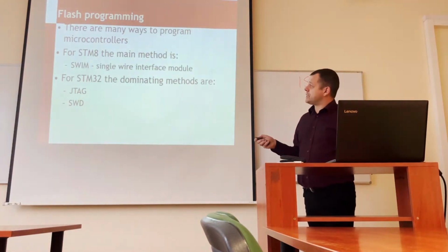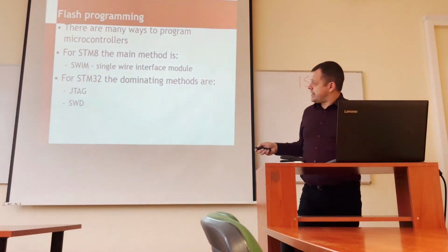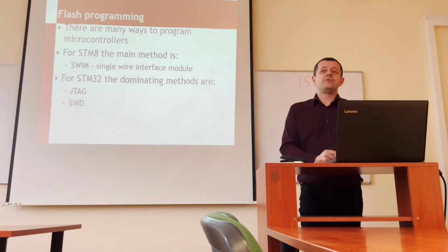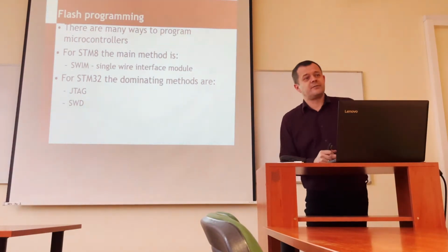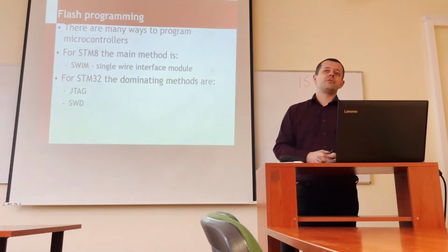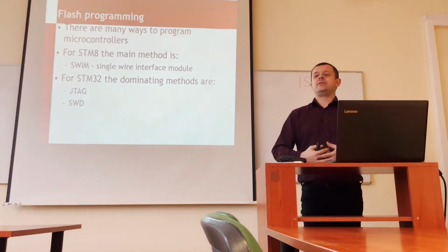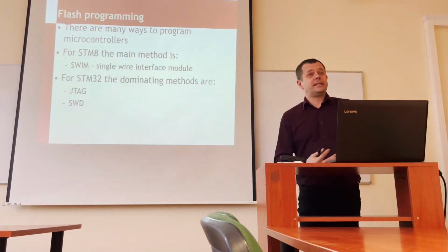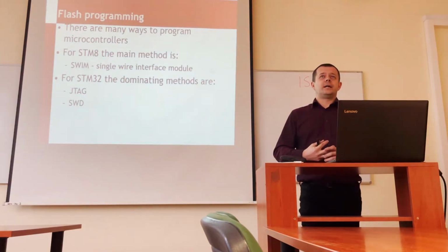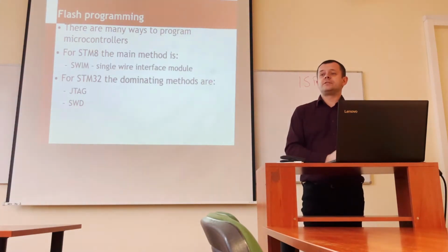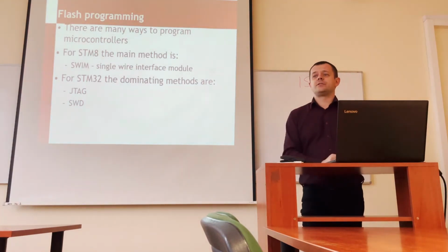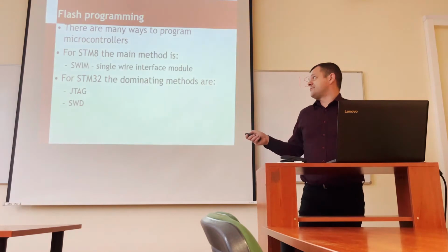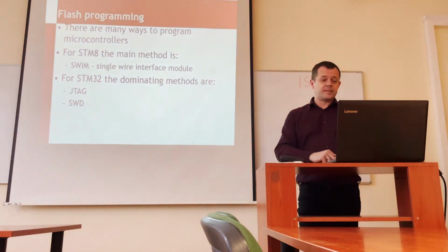Today we have, fortunately, various interfaces like SWD and SWIM that we can use for programming and for debugging, for accessing the internals of the microcontrollers. If we consider a new PCB board, it is a very good idea to use not only an interface for programming, but also an interface for debugging, even if it requires some additional hardware, which is the case for these interfaces.